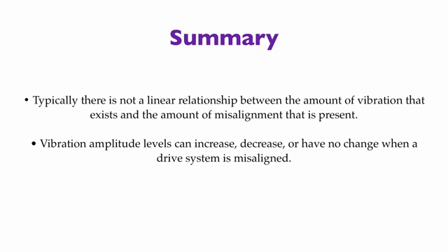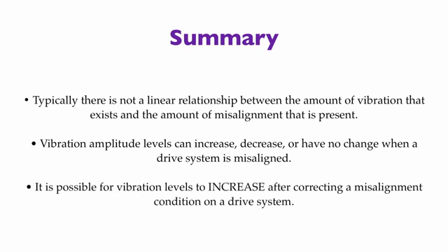Therefore, it is important to recognize that if you measure the vibration on a drive system that is operating in a misalignment condition, shut the unit down, align it correctly, start it back up, and measure the vibration again, it is possible for the vibration to increase, making it look like you did the alignment wrong.